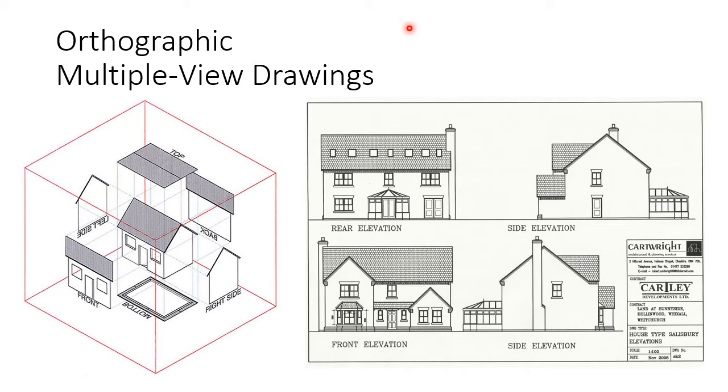The term primary view is also used, which includes the plans, the elevations, and the sections. In multi-view drawings, the drawing consists of up to 6 pictures of an object, with each projection plane perpendicular to one of the coordinate axes.